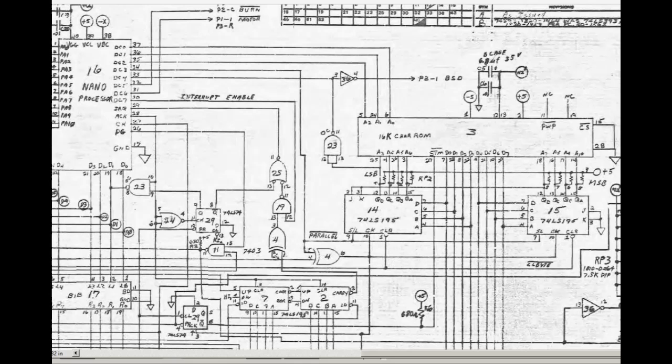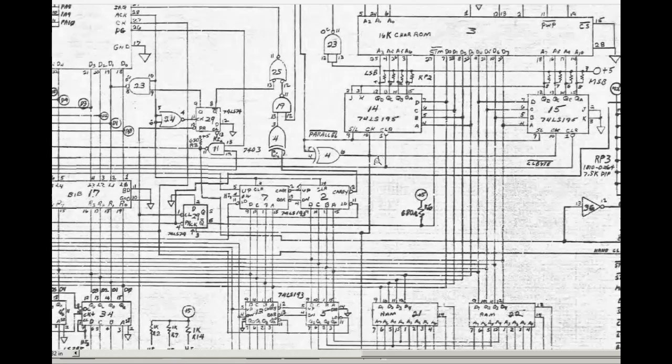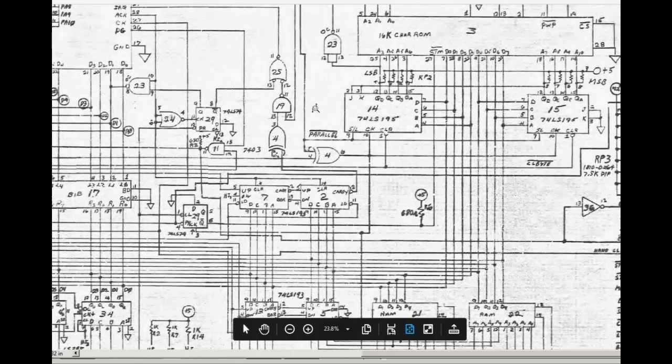Or we might select the RAM chips, in which case the RAM would then output data when the chip enable line goes low, and then on the rising edge of the clock, the data clocked into the shift register is whatever happens to be on the data bus, in this case from the RAM. We can also send data directly from the Nano processor, albeit it will be inverted. As long as the Nano processor takes that into account, it will be fine.